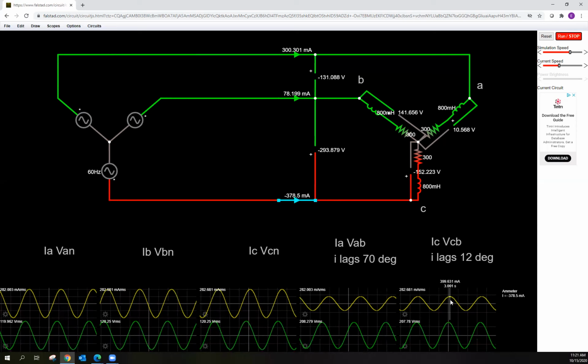Okay, let's look over this one. Look at this peak and this peak. Well, this peak here is just after, so maybe 5 to 15 degrees phase lag, but the currents are lagging the voltage nonetheless. And why? Because we have an inductive load, kind of like how we would model an induction device.